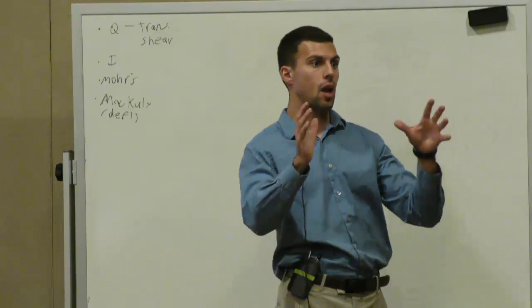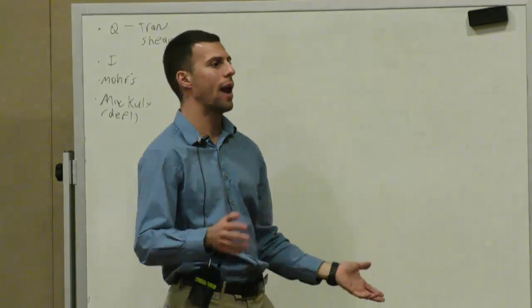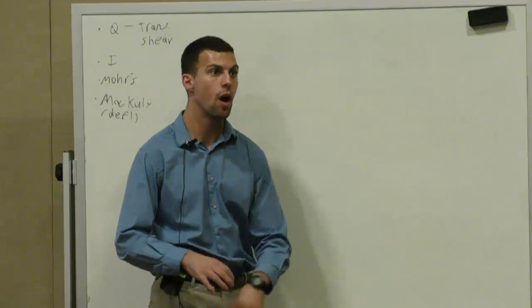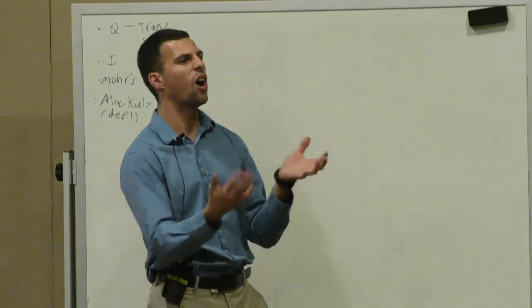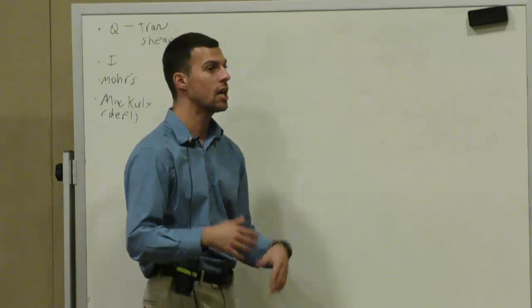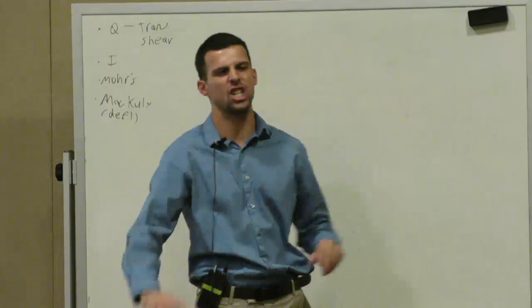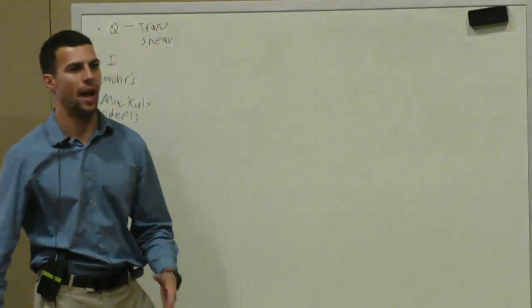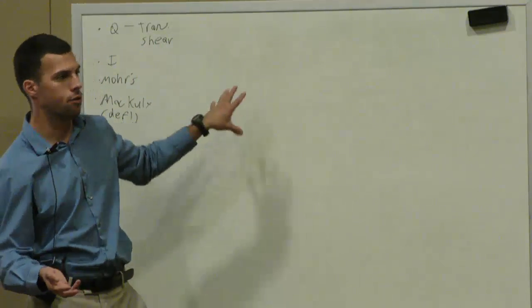What that means is you are not going to get anything extra out of drawing Mohr's circle. It doesn't give you any more information than just the equations do. However, some folks understand things better with that graphical representation. Additionally, it shows in a coordinate-system form how all these things behave, and it establishes a very pretty relationship between the rotation through which you rotate your element and the stresses that are established. It's also super useful when we get to the 3D case and the 3D Mohr circle.